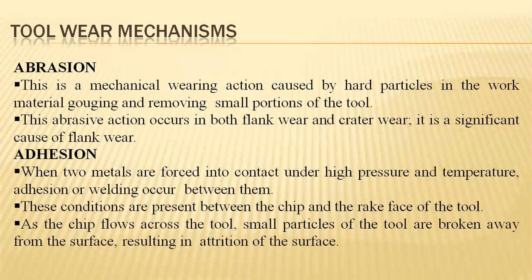Coming to the adhesion concept. When two metals are forced into contact under high pressure and temperature, nominally we look at welding processes, the adhesion welding process. At that particular time, this adhesion takes place with high pressure and temperature. Nominally, these conditions in our working processes, the MRR process, also take place between the tool tip and the surface of the object which needs to be machined. As the chips flow across the tool, small particles of the tool are also broken away from the tool surface.